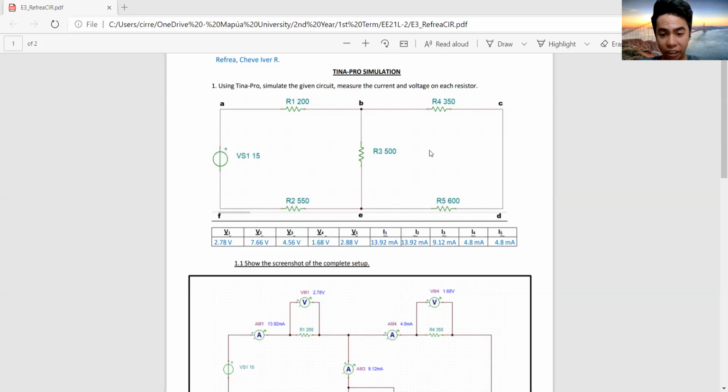The second part is Kirchhoff's voltage law. This is the second law, which deals with the conservation of energy around a closed circuit path. Kirchhoff's voltage law is the second of his fundamental laws which we can use for circuit analysis. His voltage law states that for a closed loop series path, the algebraic sum of all voltages around any closed loop in a circuit is equal to zero. This is because a circuit loop is a closed conducting path, so no energy is lost. In other words, the algebraic sum of all the potential differences around the loop must be equal to zero, as the summation of V equals zero.